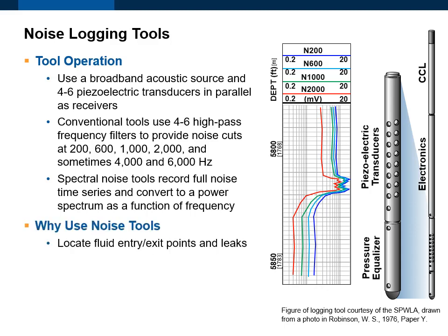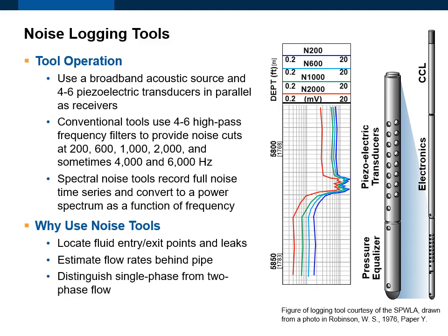We can use them to locate fluid entry and exit points and leaks. We can sometimes estimate flow rates behind pipe. We can distinguish single-phase from two-phase flow. We can do range finding from blowout relief wells.